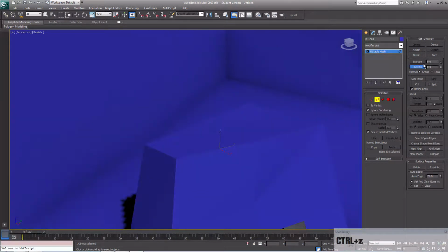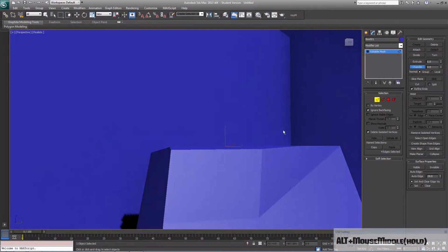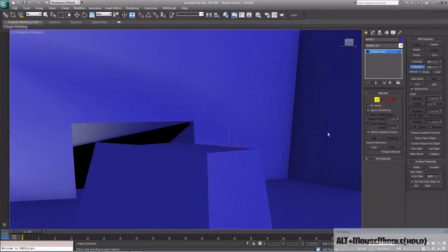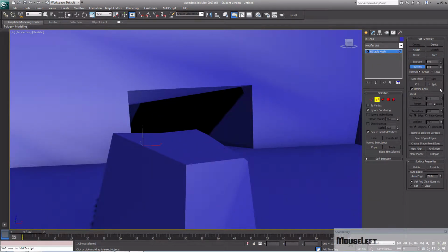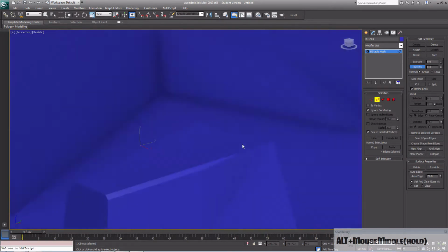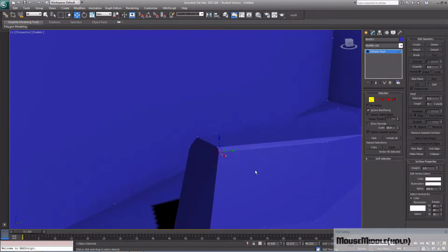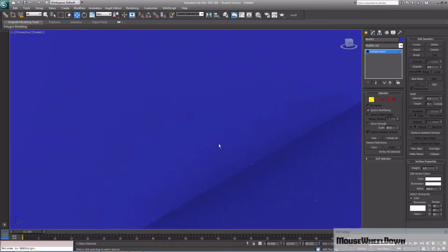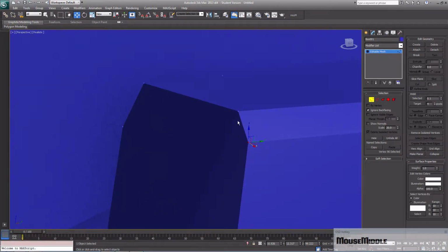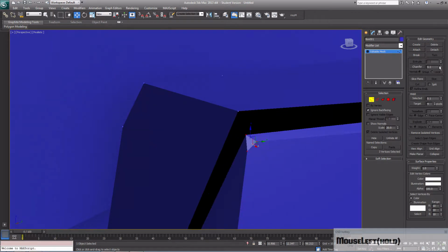I need to click out of it and just change it by number, I think, because it's really sensitive on that. There we go. So you'll see, instead of having these really sharp corners, now you have that. And I'll change this one as well, so you can get a really interesting looking base. And it's worth noting you can also chamfer vertexes. So if you see where this vertex meets at a point right here, you can even soften that up.